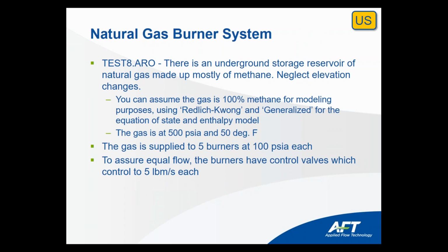So we're going to leave Redlich-Kwong, all of that. Now the gas is to be supplied at 500 psi absolute and 50 degrees Fahrenheit. We have 5 parallel burners here, and each of those at 100 psi each. So the flow must be equal here.